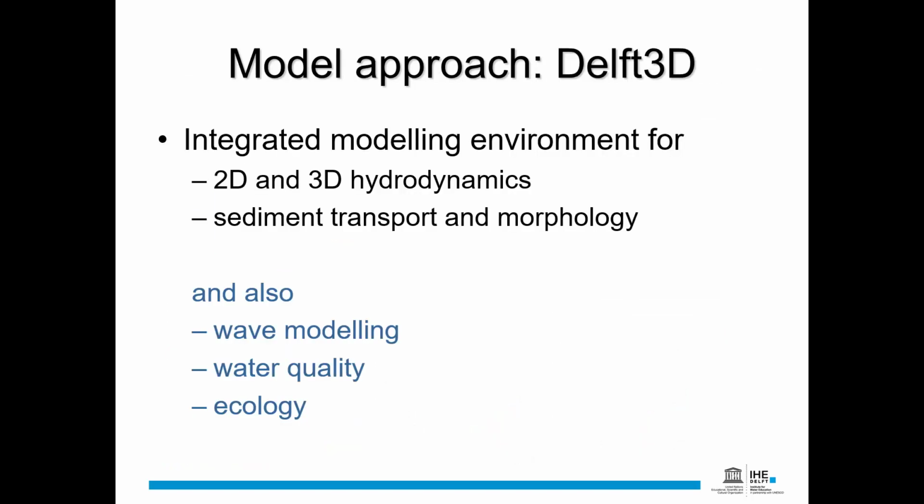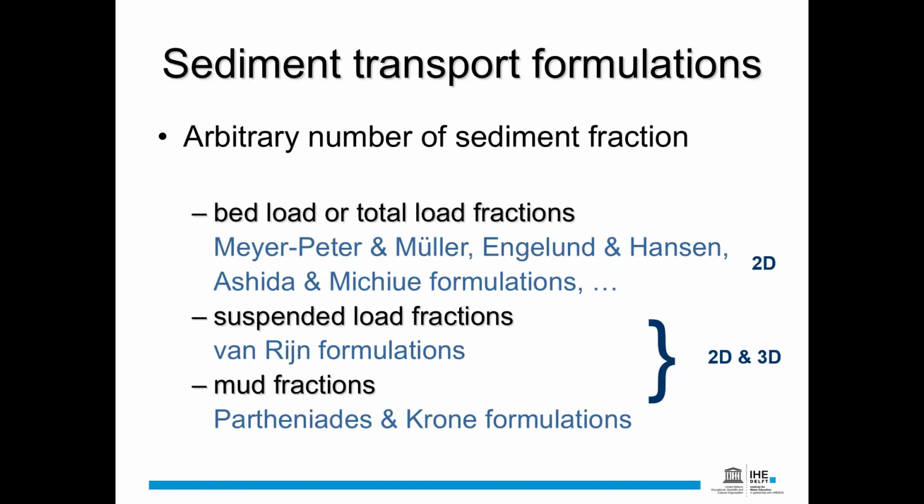Maybe good to repeat that Delft3D can do 2D or 3D hydrodynamics with sediment transport and morphology, and also you can impose wave models, water quality, and ecology on top of it. But now we are focusing on the sediment transport. In Delft3D, we can use many different types of sediment transport relations. For example, we can look at the Meyer-Peter-Müller, Engelund-Hansen, Ashida formulations, or we can, if suspended load is more important for us, then we can look at the Van Rijn formulations.